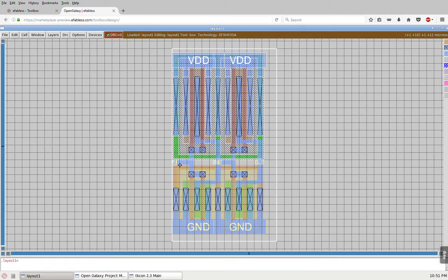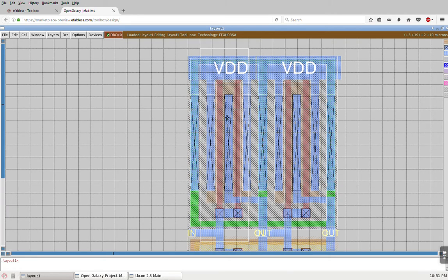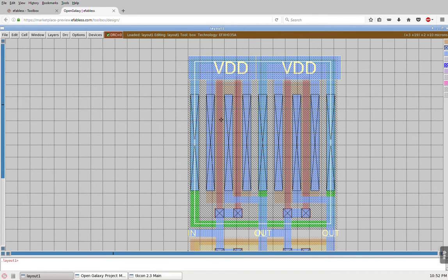If you want to measure the device, actually, there's a very easy way to do that. You go and put your cursor above the area of interest. I'm going to hit S. Now, first time it's not what I want. I want to get that gate. So I'm going to hit S repetitively until the gates get selected. And here's the gate over here.